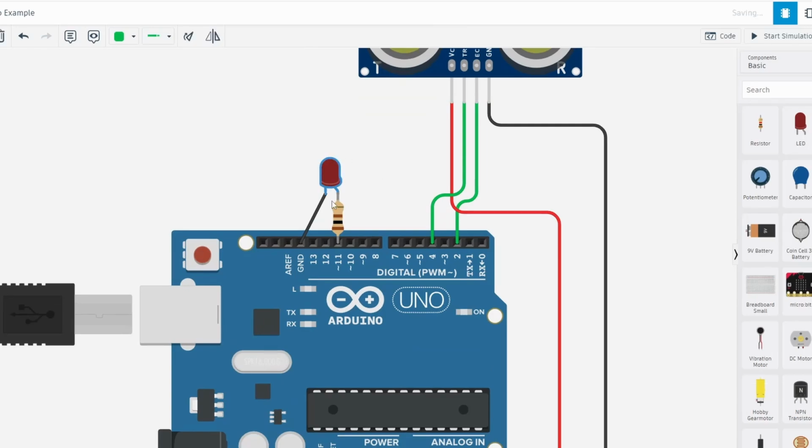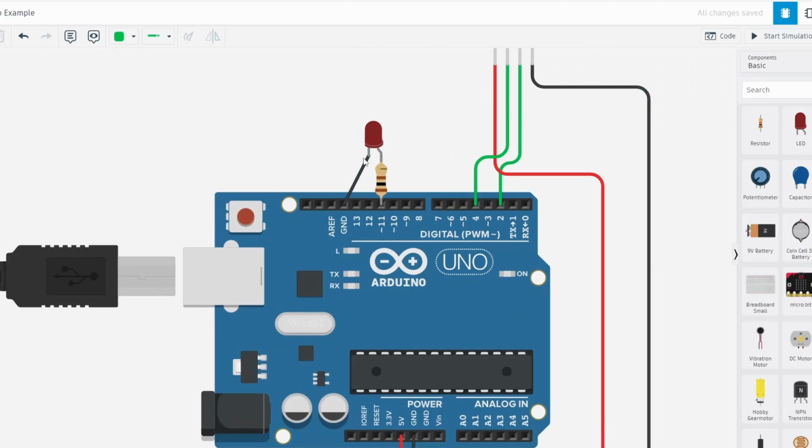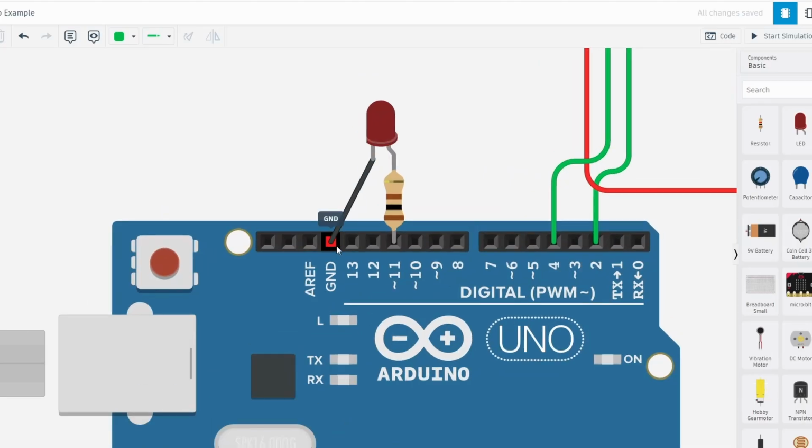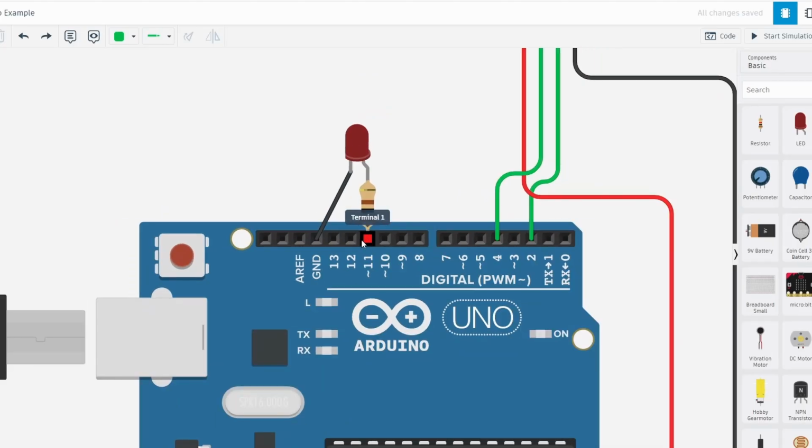Here we have a recognizable LED with a resistor in front of it. And as we saw before, that resistor is meant to reduce the current going through this LED so that it doesn't blow it up. And then this wire here just goes to the opposite end of the power supply. So you can think of this as the negative side of a battery, the ground, and then this side as the positive. And as you've seen before in the microcontroller animations, we can output a voltage or a signal from these pins over here, and that can create a current.